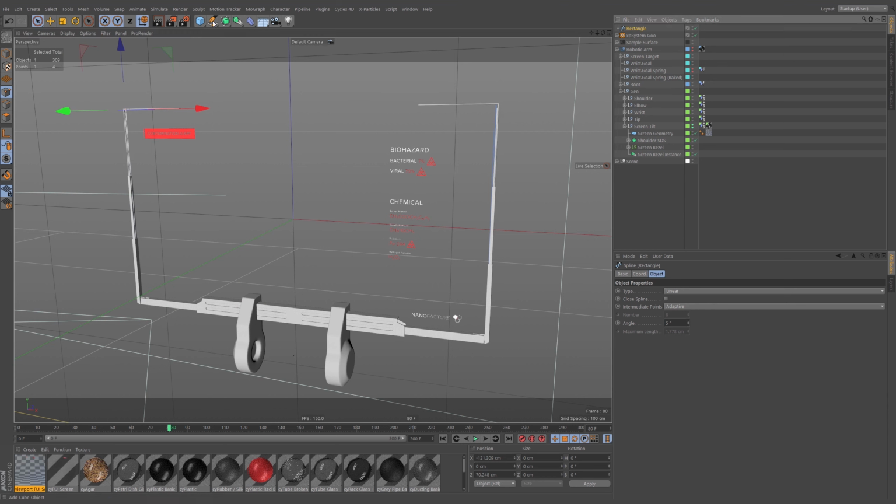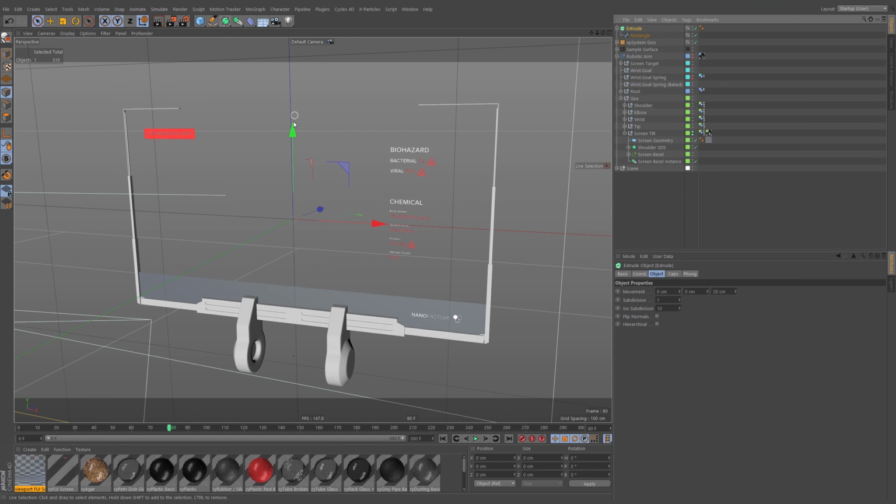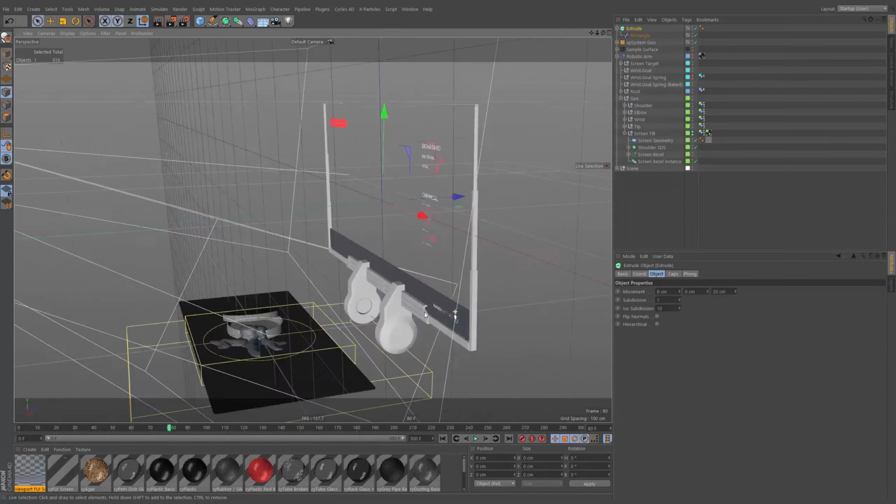And I'm going to add this rectangle to an extrude. So go up here, and there are these, what used to be called NURBs, but they're generator objects to generate geometry from splines and subdivide and stuff. So we're going to grab the extrude. I'll hold Alt down whilst I add it, whilst I have my rectangle spline selected, and it'll make it the parent.